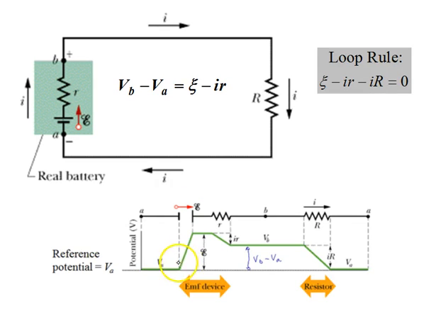And we can look at that linearly if we have our reference potential here at VA. As we go across the EMF device, we'll model that as increasing linearly until we get to the other side of the EMF device, and then our potential will be at E, whatever our EMF is. And it will not change, and this little equal potential here will have no change in voltage until we get to the resistor. Across the resistor, internal to the EMF, we have a potential decrease.